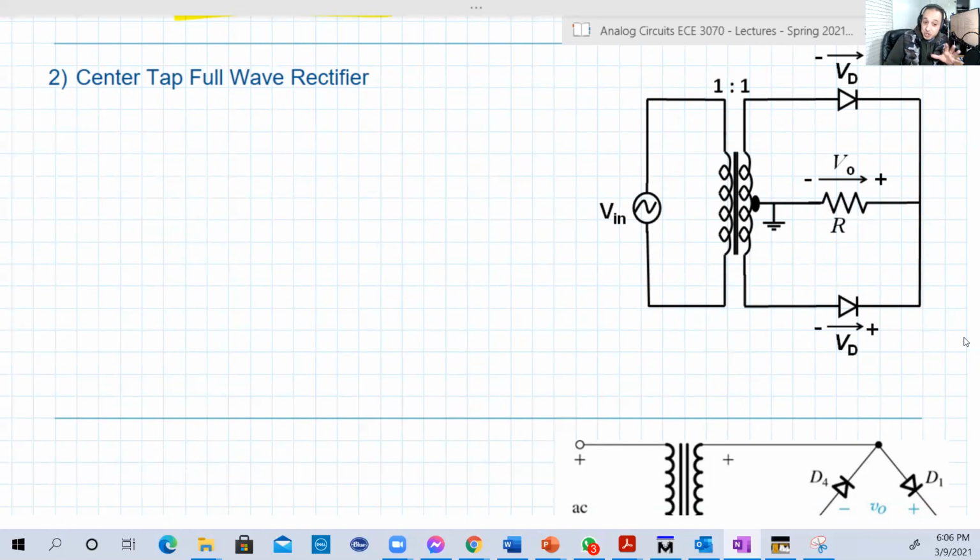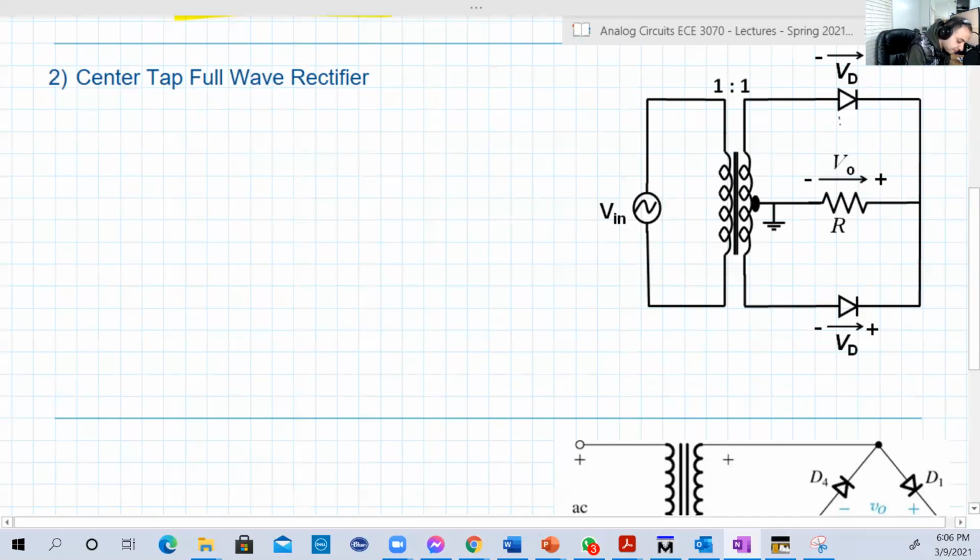I mean, if you choose to calculate the peak inverse voltage for D1 and it was with some value, let's say minus 100 again, then it should be the same for diode 2. So you can do the same for diode 2 and you should get minus 100. If you get something else, then you have some mistake. Okay, so let's do that. So if this is D1 and this is D2, let's do that for D2. So calculate or find VD2 when V input equal to Vmax.